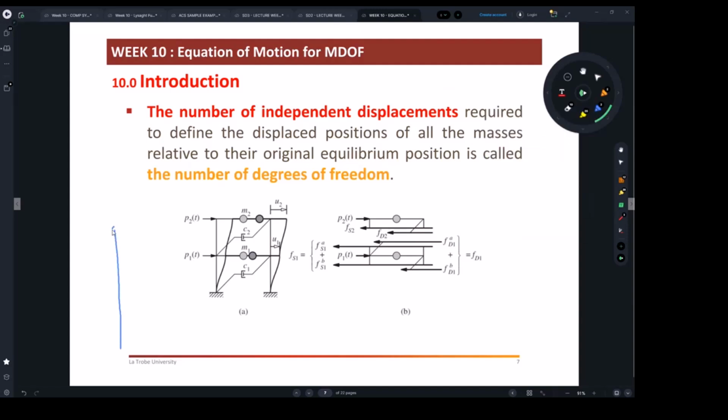So if this is again a multi-degree of freedom system where you've got, say, 5 or 6 masses, which I'm putting for you here, and this is your base, and we're going to be shaking the ground here, now each mass can freely go to the left or right. That's also going to help you understand what's happening next week, because these kinds of simulations will let you determine the mode shapes.